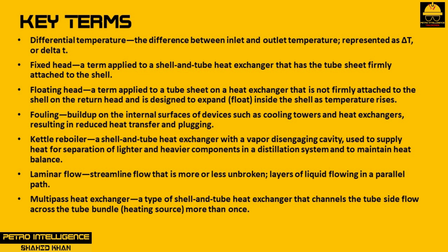to the shell. Floating head is a term applied to a tube sheet on a heat exchanger that is not firmly attached to the shell on the return head and is designed to expand or float inside the shell as temperature rises. Fouling is buildup on the internal surfaces of devices such as cooling towers and heat exchangers, resulting in reduced heat transfer and plugging.